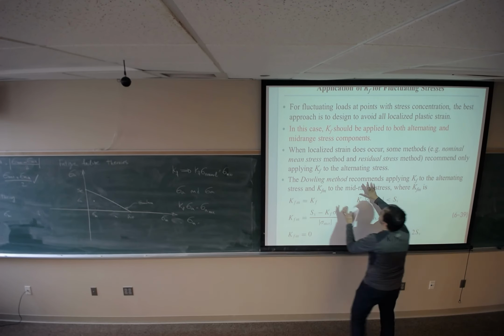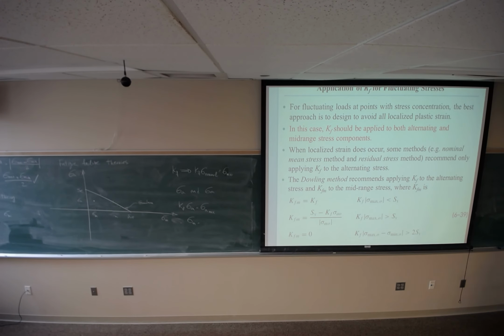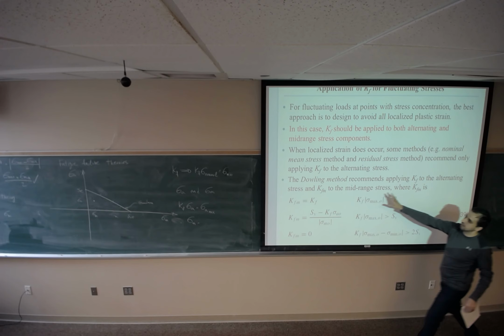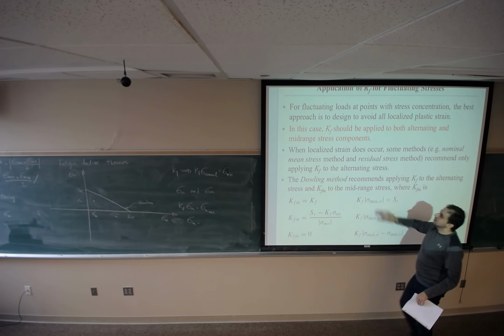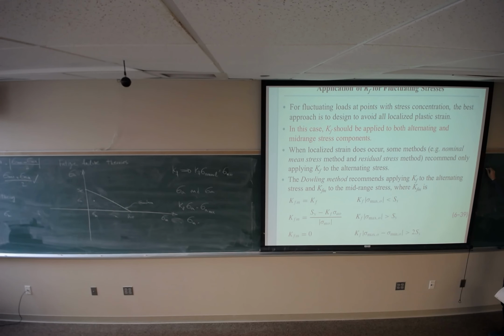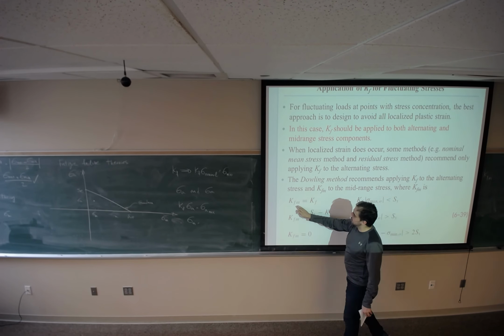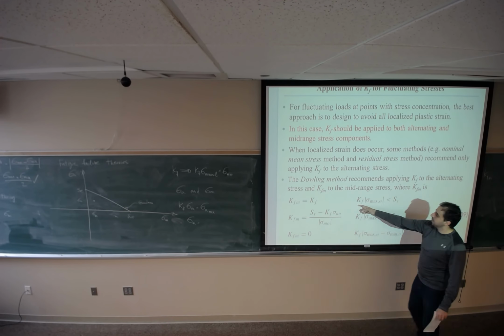There are some methods for dealing with this problem. We are using this one, the Dowling method. It defines Kfm, the fatigue concentration factor for a mid-range stress. Kfm is going to be equal to Kf if this is valid.